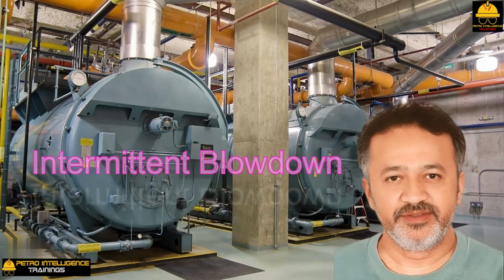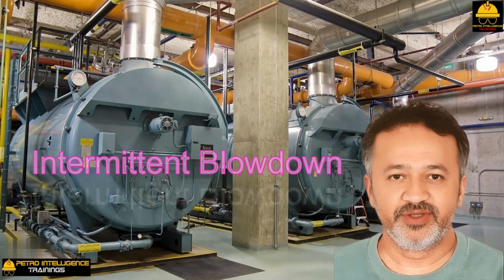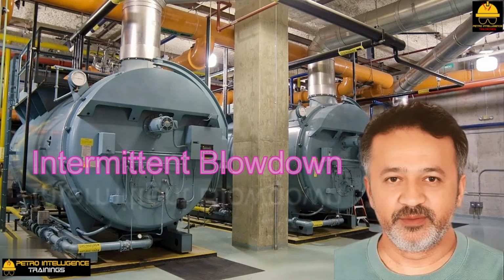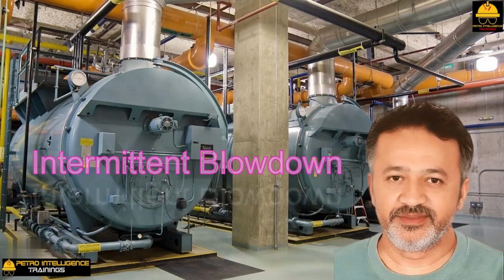Intermittent blowdown. This blowdown from the mud drum of a boiler is usually once a shift via a manually operated valve. If this is automated, it is important to have the valve fully open for short periods to keep the valve clear and unblocked.